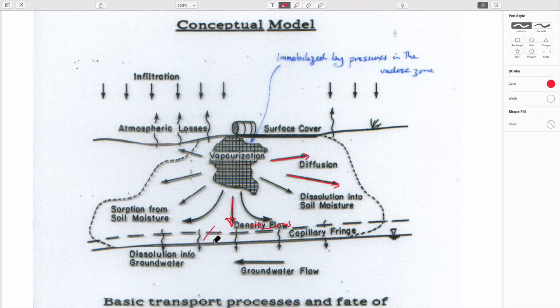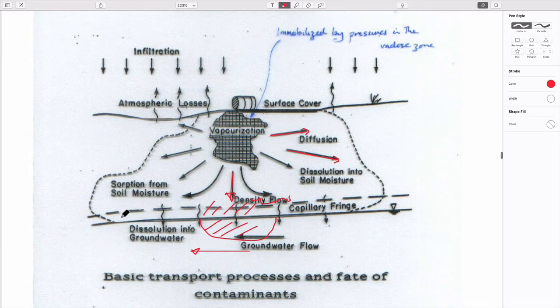Once it's in contact with the water table, there's no reason why it can't dissolve into the aqueous form. And if it dissolves, there's no reason why it can't be carried downstream in pre-existing groundwater flow, driven by a slope in the water gradient. And this diffusion and advective flow can also be affected by the amount that is taken out and attached to the vadose zone aquifer, and then lost to transport.